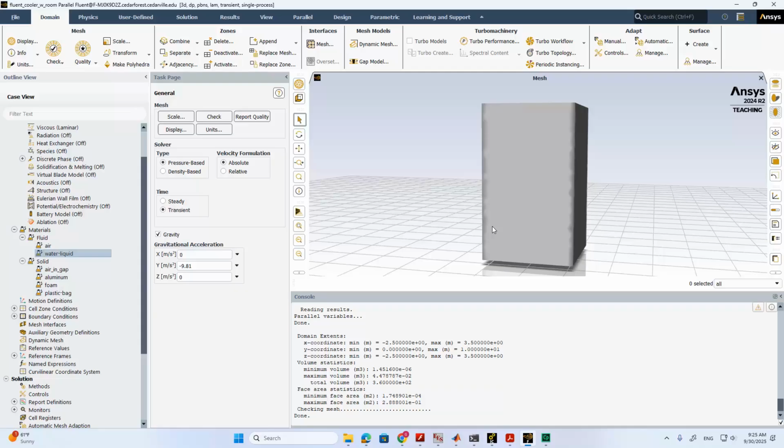the insulation foam and the aluminum container. Because those two surfaces are not perfectly smooth, there are always some gaps in between them, and air is present in those gaps. You can see that I add air in gap as a solid material.